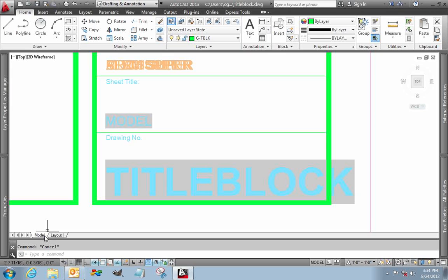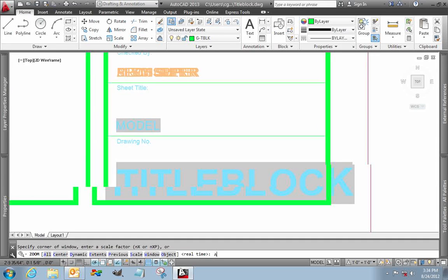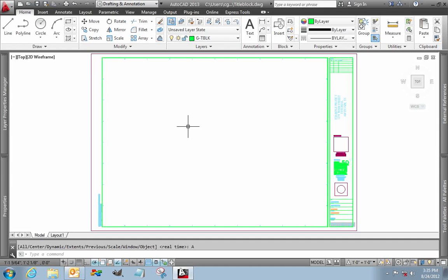So in your sheet files, the text that says ground floor plan or level 3 floor plan or level 7 electrical lighting plan would go in the tab down here, and then this piece of text would accurately reflect that. So that's it. That's creating a project-specific title block. We've used the template, we've saved it to the project folder, and the title block is done.